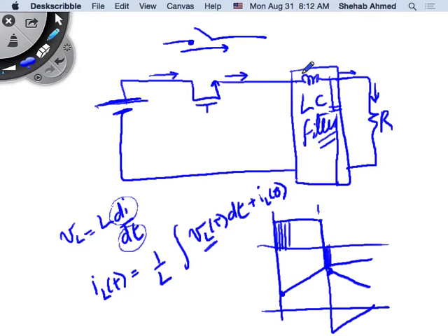With Kirchhoff's voltage law, the sum of voltages has to be zero, right? So this plus this plus this plus this is zero. This will not change. This will not change. This changed and increased considerably. So something has to be equal and opposite to this voltage in the circuit. In this loop.